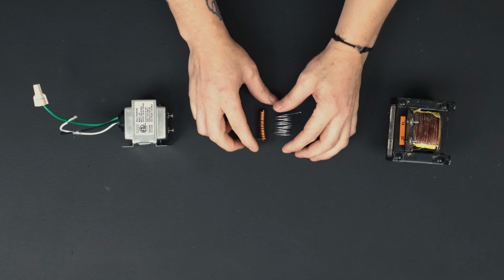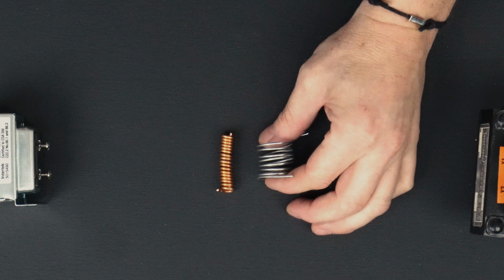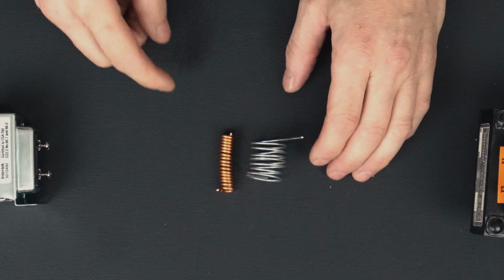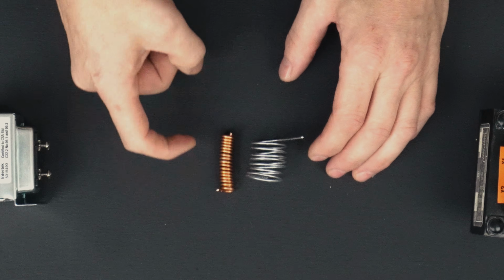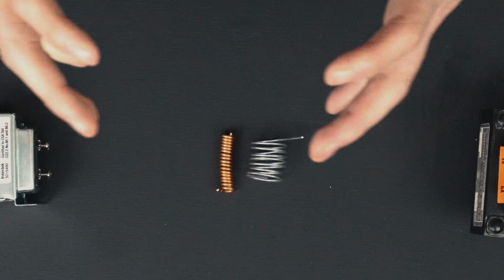So they're kind of set up like this, in a way where our input comes through one of these coils and our output goes through another one. There's some like magical, mystical stuff that happens. Not really. But when you have electrical current that's going back and forth and alternating, you can make an expanding and collapsing magnetic field around the conductor. If you have DC, this doesn't happen because you just have current going in one direction, so it's not constantly